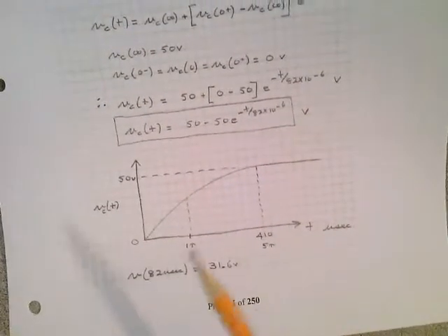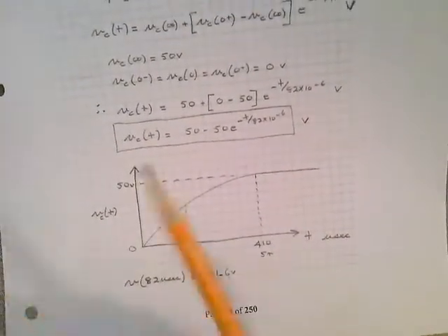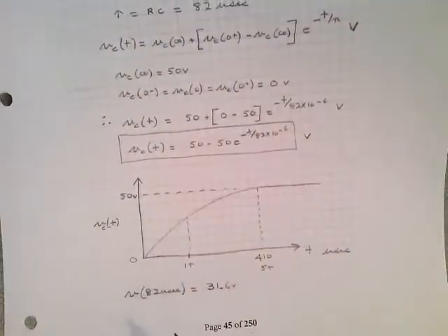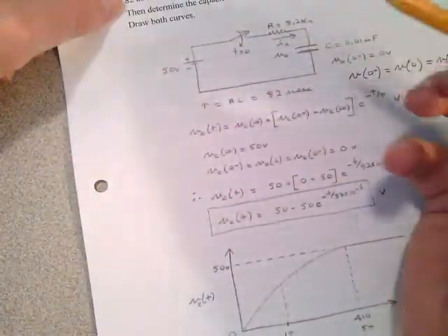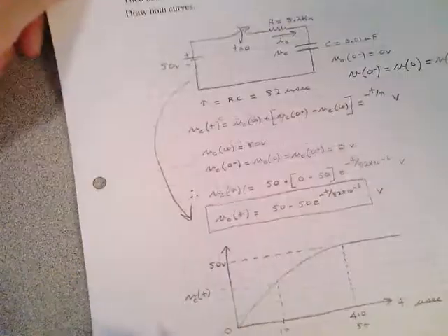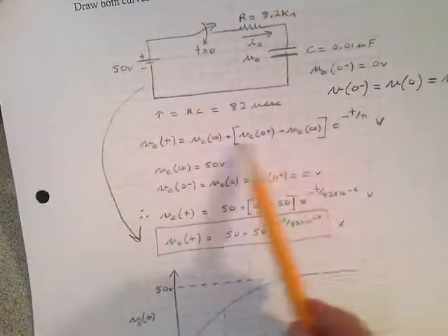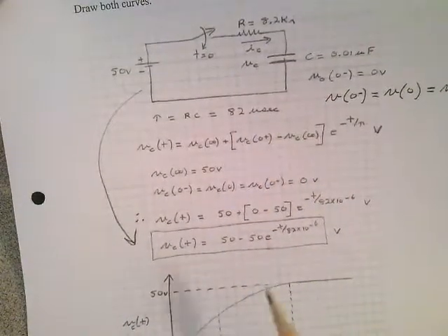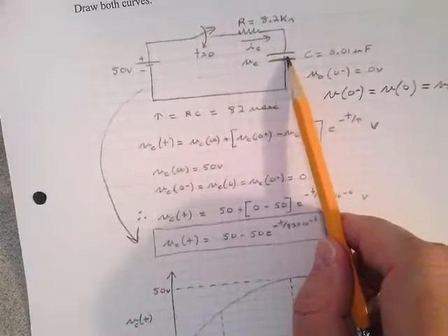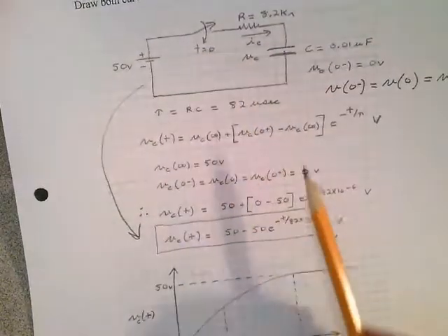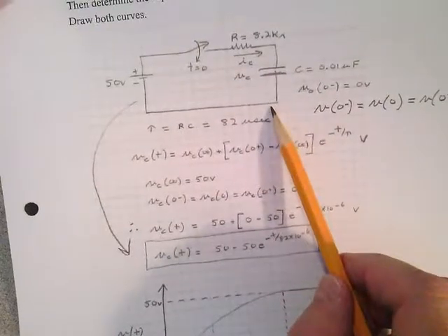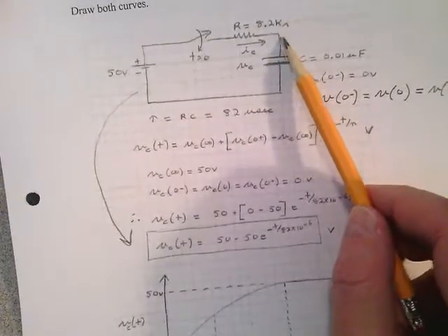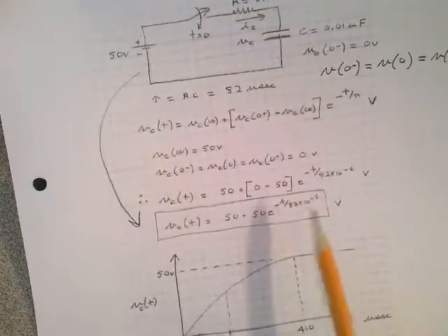And compare that to how many time constants that would be. I mean, you can relate this other ways too, but I'm showing you the way to look through this using this equation. I think you could probably go straight from this circuit to that equation without doing all this. But I want you to do this until you understand it before you go from here to here. Now, how can you go from here to here? Well, you're looking at the voltage across the capacitor. You want to know the voltage across the capacitor when you throw this switch. Is it going to have a final value or not? Well, sure, it's going to have a final value because it's going to look like an open circuit at t equal infinity. So you're going to have a voltage there with respect to here. So it has to have this shape, which leads you to that form.